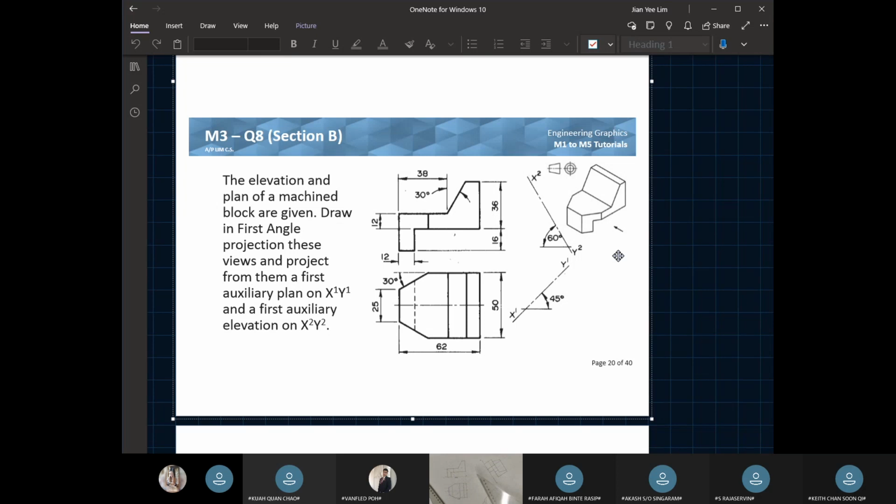Then for the second one, the x2 and y2 is flipped upon this datum. As you can see, the datum is 60 degrees, because the angle on this set square is 60 degrees. So this line is 60 degrees from the normal, and you'll be reflecting this view from here. How you know x1 is view 1, the number 1, then x2 is number 2.